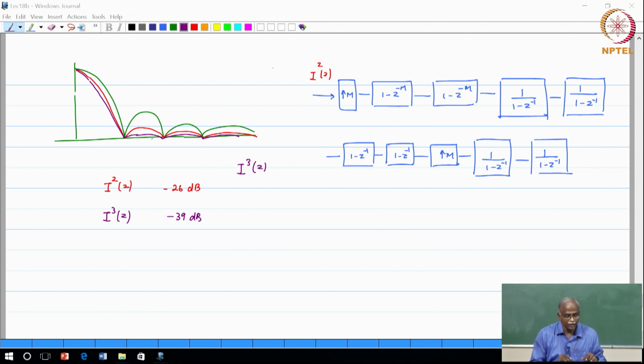Phase problem? See, again, these are effectively linear phase filters, because all the coefficients are equal to 1. So, anytime you square them, the phase is still linear phase, but with a different slope. So, these are actually filters which are very well behaved in terms of phase as well. They are, in other words, constant group delay filters which give you multiplierless responses and very good performance.